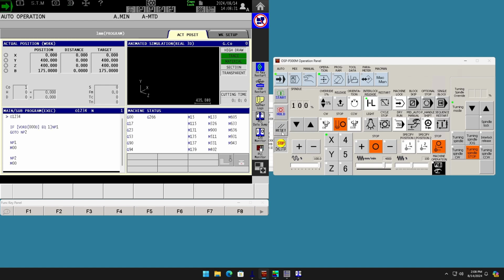An operator puts a new tool in their machine. Well, part of that process for them was to go into the tool library, go into the tool life manager, find that tool that they just put in. Do not confuse that tool with another tool that's the same tool group, because that happened a lot. Restart that tool counter value and reset that tool to good. That's a lot of steps for an operator, especially somebody who's not familiar with the machine.